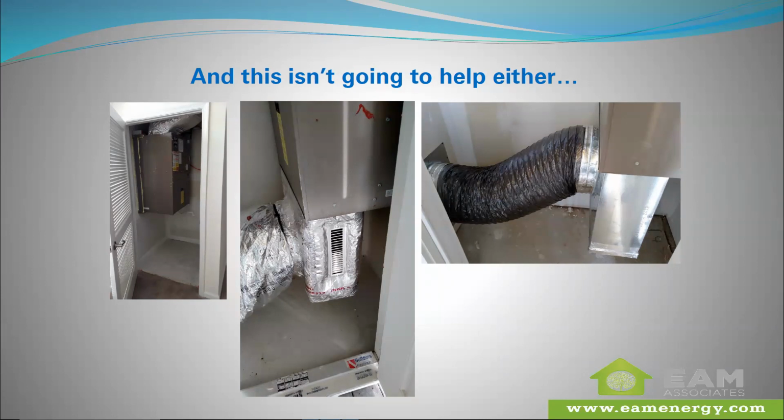Those mechanical closets in these style buildings are at best a sort of waste conditioned, semi-conditioned space. So cutting that return in there was really, this is an exterior type door with weather stripping. But actually when we arrived, they were letting the tenants have access to mechanical closets. They weren't locked out of them. So people were putting stuff in there. They were opening the door and not always closing it, or at least closing it properly. So you have this return in here now that is just sucking in outdoor air directly into the system, and obviously pulling in all that humidity with it.